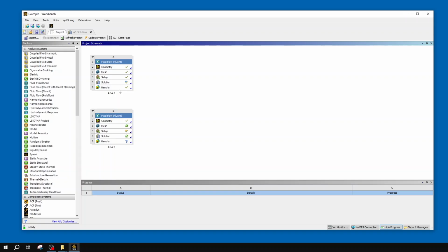So yes, that's the big advantage of using Workbench. Quite a long process to get your first iteration, first angle in this case, running, but it makes it very convenient for my subsequent angles where I just have to duplicate these a bunch, change that one factor in my geometry, click update, and it'll run through all my different variables. So again, I hope this helps whoever's out there looking to use Workbench and Fluent in general to run their programs.